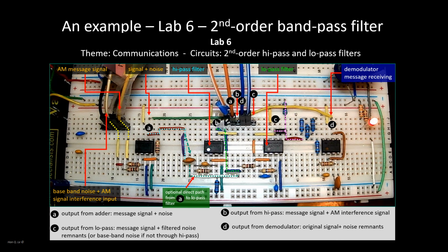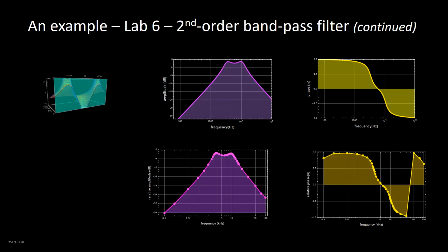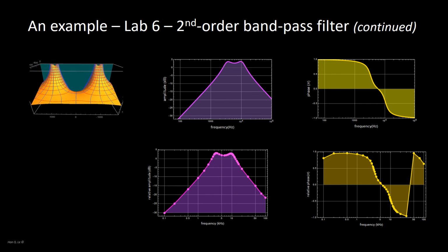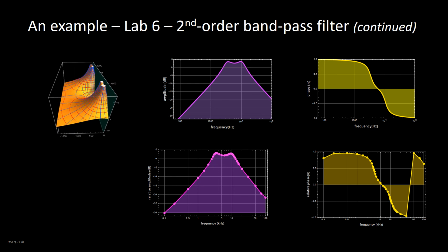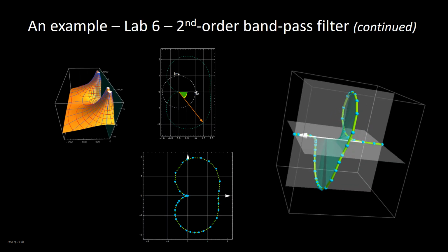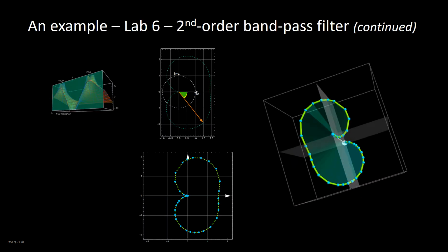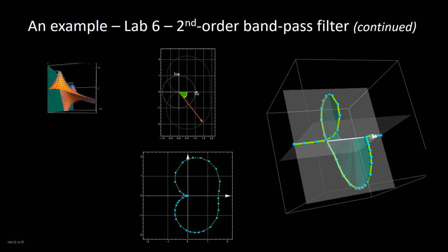The top graphs are theoretical, or designed, frequency responses. The bottom graphs are experimental results. The agreement between design, top, and measurement, bottom, assures that the circuit was built correctly. This is the same as in the previous one, except that the results are graphed with a Nyquist plot instead of Bode.